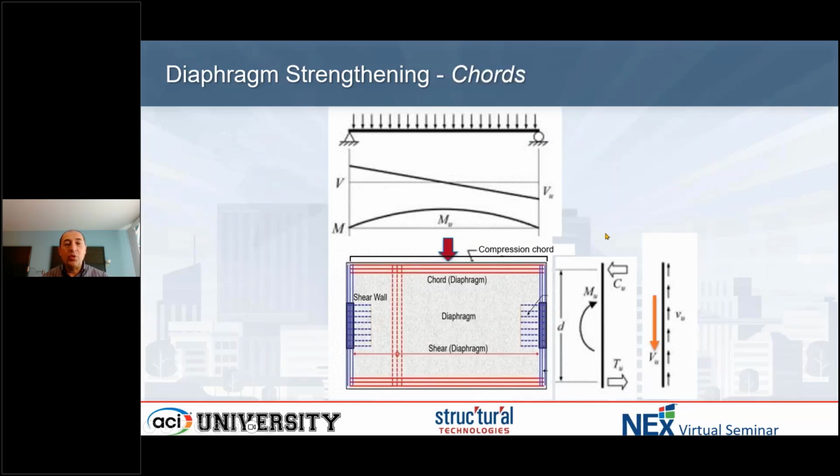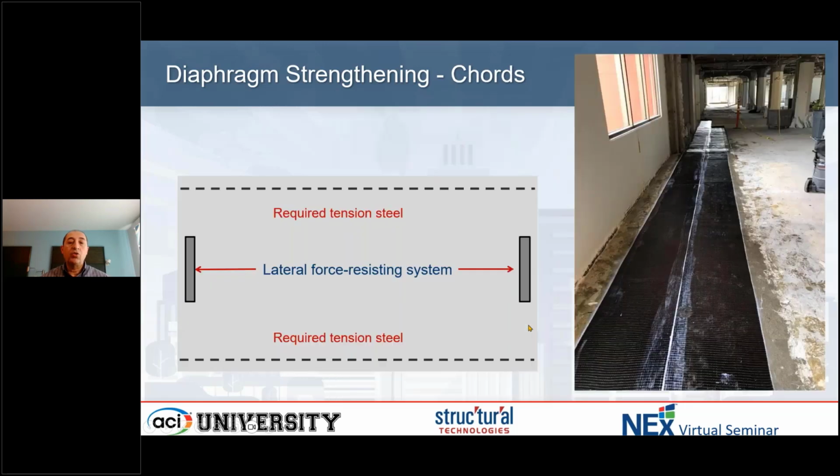Again, I was trying to put this together very quickly, so it's not the best schematic, but I hope that everyone will be able to understand. If I imagine this slab in the horizontal direction, like a beam, it will be exposed to bending moment, like I mentioned, and shear, and that will create demand in tension, as well as shear demand and, as I mentioned, in transfer.